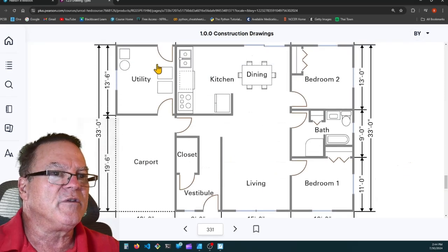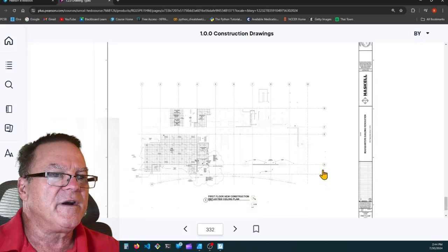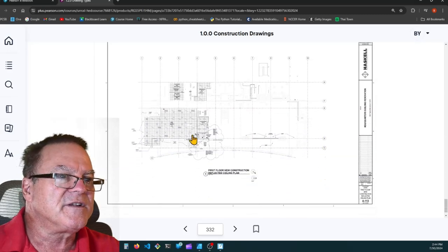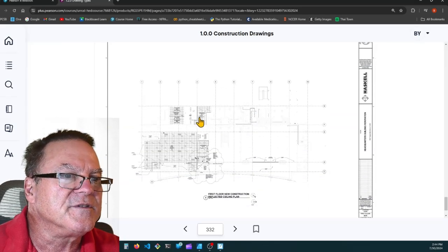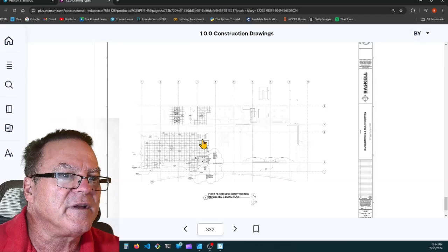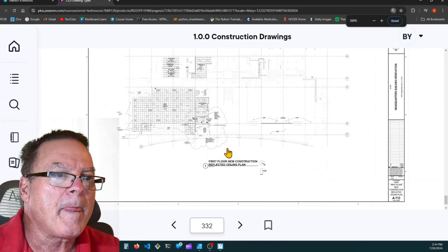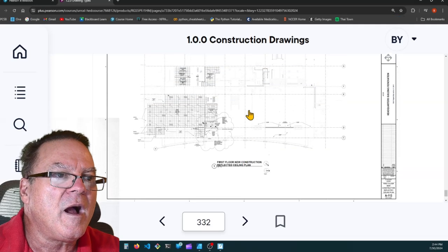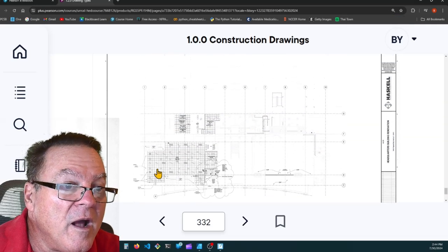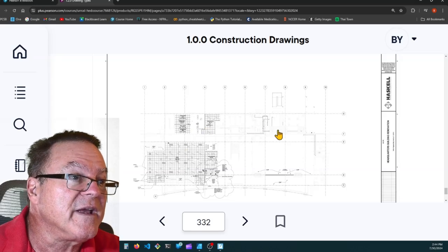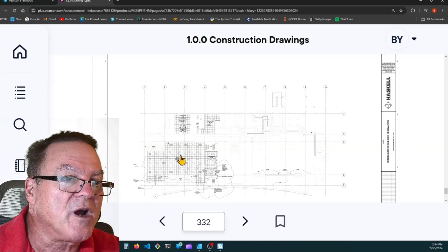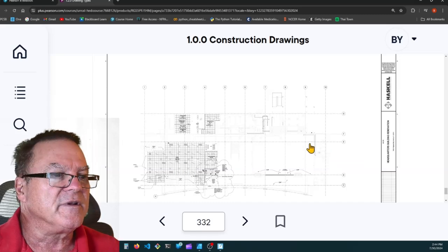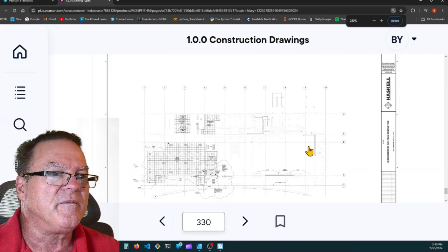So here's your floor plan. And then when we go here, here's the reflected ceiling plan. Well, it's a shame this isn't the same drawing at all. They're using a different drawing here for the reflected ceiling plan. But yeah, this is too small. We can't get any detail at all. I was trying to show you that these are 2x2 grids, drop-in lay-in ceilings with 2x4 lay-in lights, but you really can't see any detail in that. It's too small.